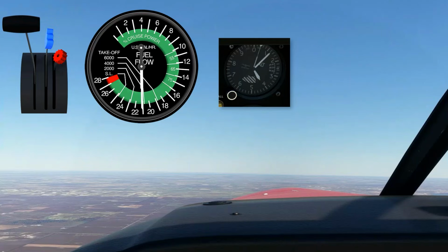You don't have to do this continuously. You don't have to do it constantly and really stay on top of it. Every 1,000 feet or so is fine. Just tweak it back close to the line that's appropriate. And of course, verify that the CHTs are in a safe range, because if they're too hot, then you probably need that extra cooling, that extra fuel for cooling. These sorts of markings, if they're not directly on the fuel flow gauge, may be in your POH, or may be on a placard in the panel. But if your manufacturer has done the work for you, test it out. This probably works just fine.